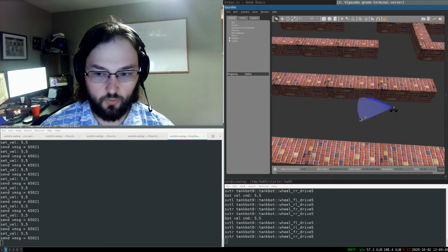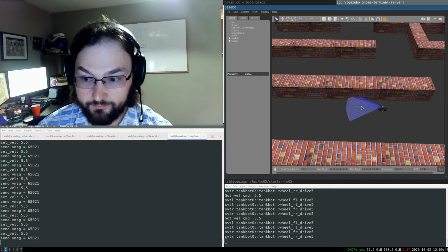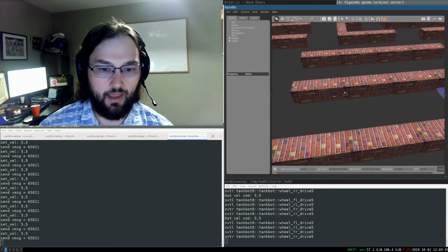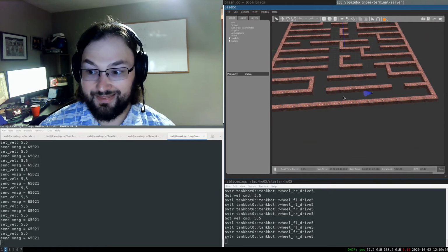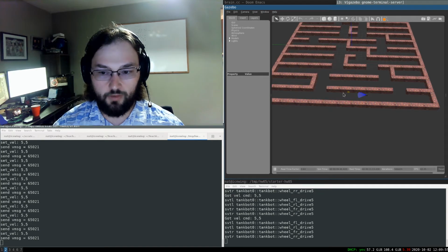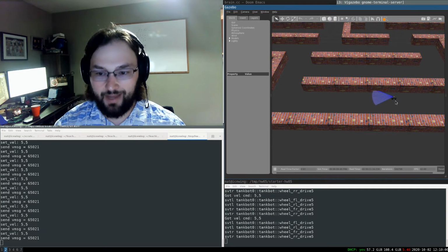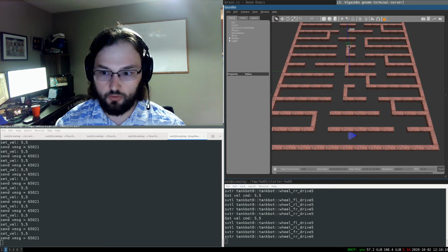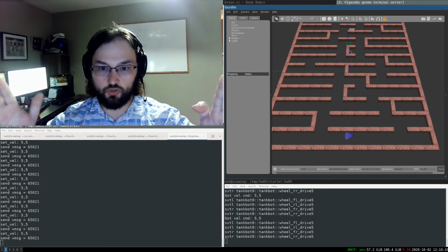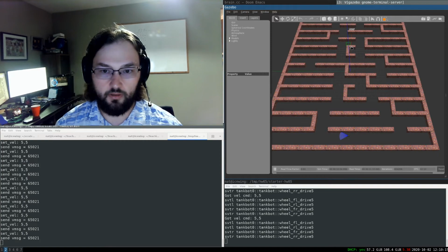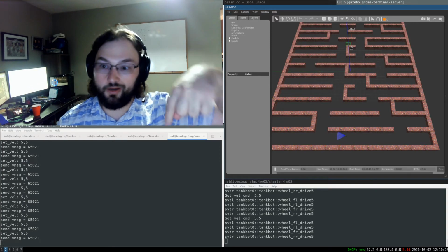So the next step here would be to try to detect the case where we hit a doorway, and then decide whether we want to drive through the doorway or not. And once we get into having a doorway detector, that ends up actually being sort of neat for trying to do mapping, because we can keep track of whether or not we went through doorways. We also have angle information, so we can keep track of which direction we're going through the doorway. So going through a doorway sort of towards the goal, the same direction we started facing in, can be meaningfully different in our control program than going through a doorway away from the goal.